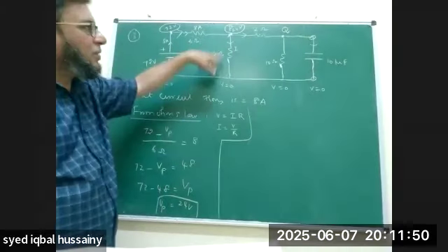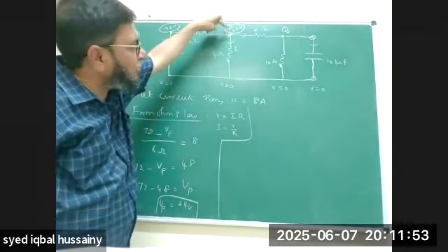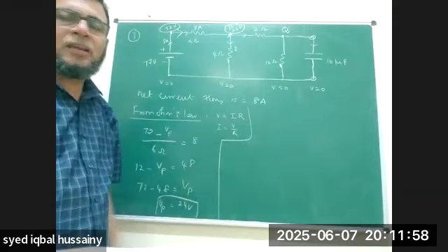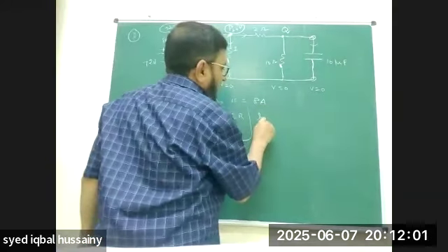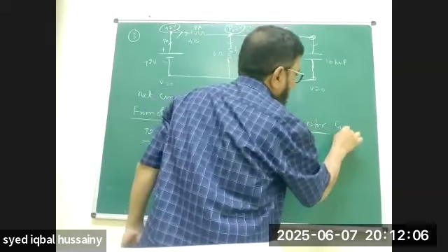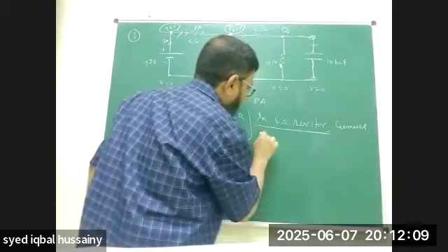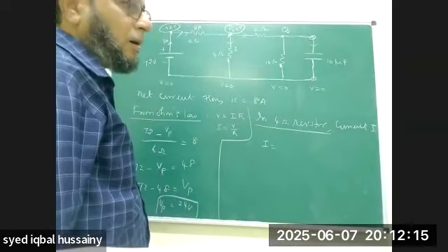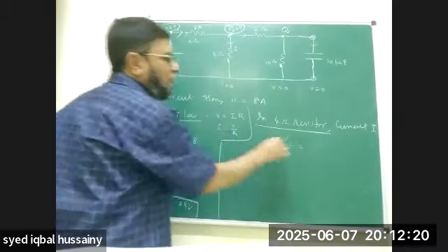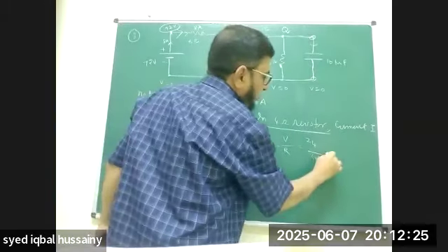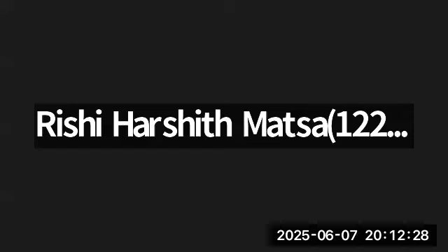So how much current here? See, the potential difference is given. The high potential is 24, the low potential is 0, so the potential is perfectly given and the resistance is also given. So what is I? Can you say, for the 4 ohm resistor, what is the current I? I equals what? The formula is I equal to V by R. So what is V? V is 24 volt in this track alone. Very simple, so 4, how much? Quickly. 6 ampere.